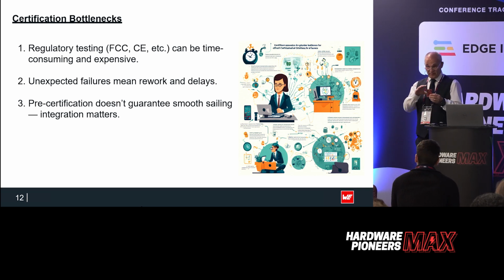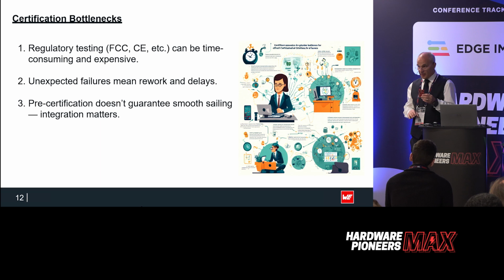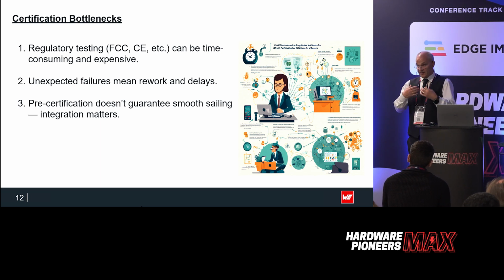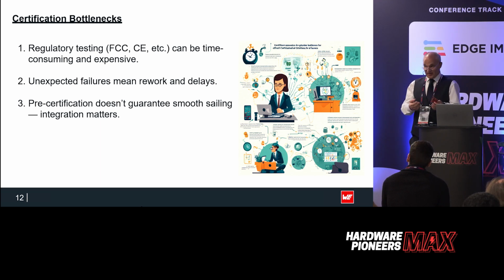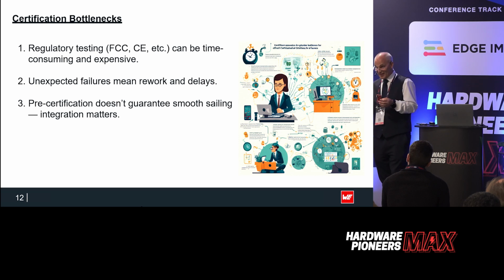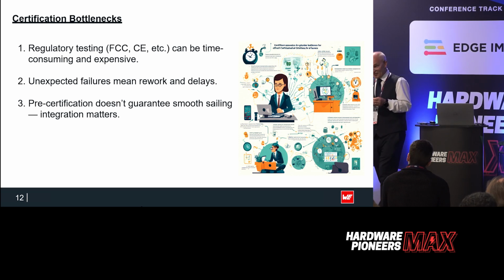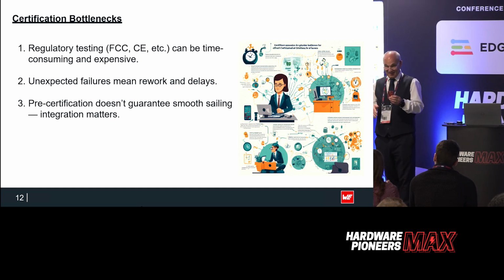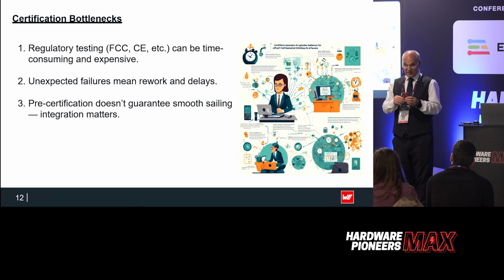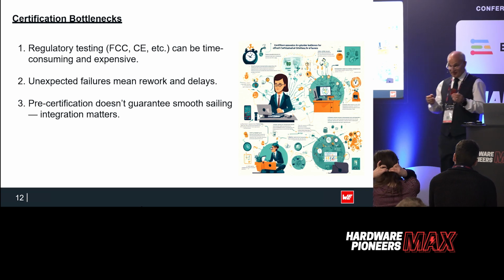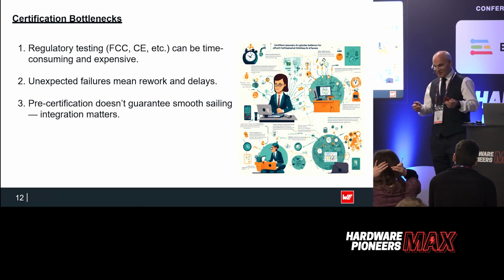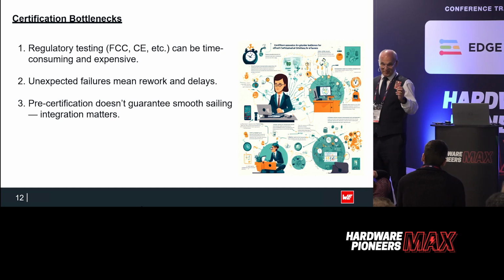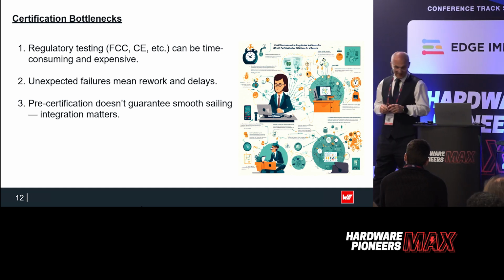So although you've got the radio protocol working as you expected, you would have to then write a test procedure. Otherwise, if you're only transmitting for 1% of an hour, that's 36 seconds, and you're testing 360 degrees in horizontal and vertical polarization, your Eurofins or Element test house will be very grateful because they're going to earn a lot of money out of you guys.